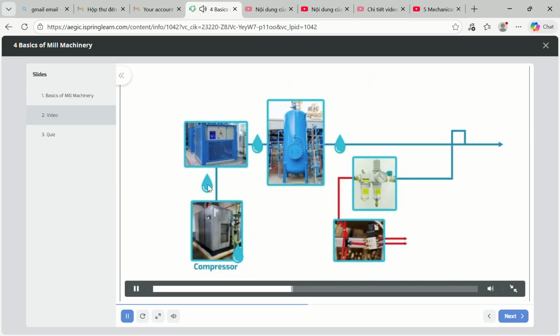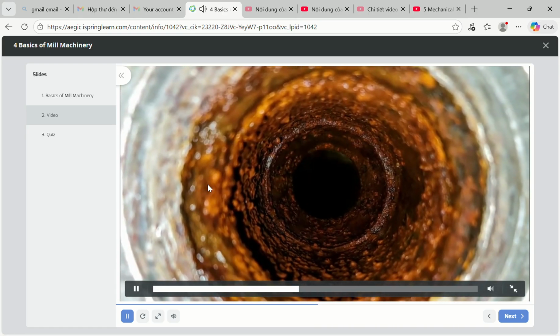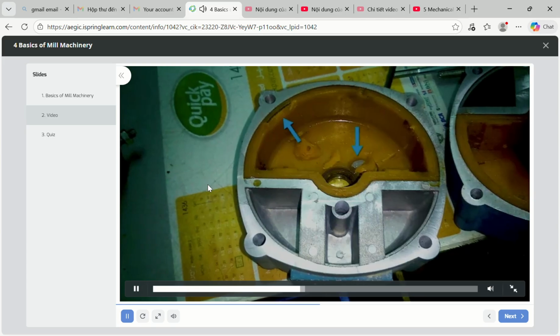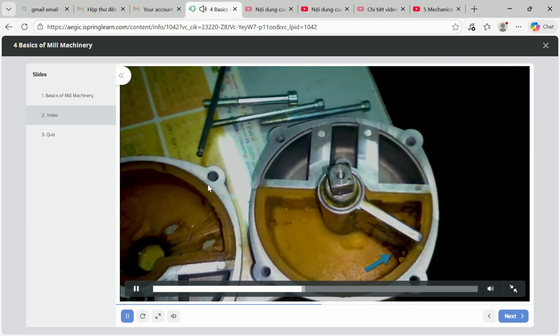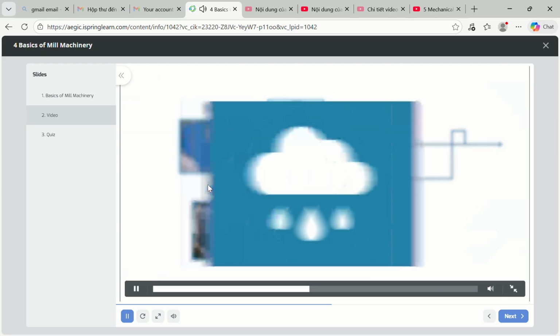Compressing the air also concentrates the water vapor in the airstream. Depending on the relative humidity and pressure, this moisture can condense, resulting in rust, accumulation of debris in the air circulation system, and coalesce with other impurities that can cause damage to the process. Compressed air passes through a central dryer to extract some of this water before entering the plant. Dryers should be regularly drained. In humid climates, controlling moisture levels in the compressed air system is particularly important.